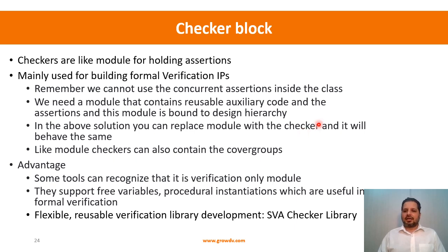The main advantage of using a checker is that some of the tools can recognize that it is a verification only module. Bind leads to instancing, so when you look at the hierarchy and click at the location where you are bound, it will show up as an instance there. When browsing that hierarchy, you might sometimes feel confused about why this module is coming in over there. In such cases, some tools recognize that if you put it as a checker instead of a module, they will give a symbol to tell you it's a testbench component and not a design module.